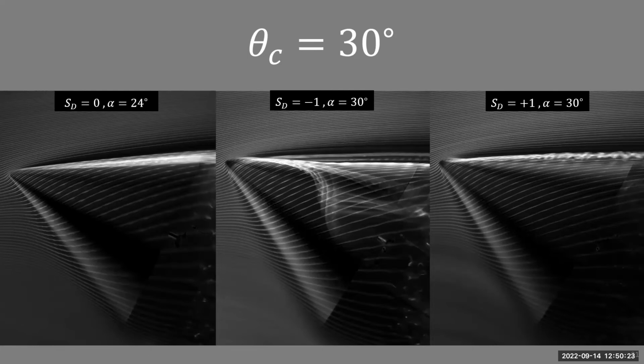So if we go back to Kobayashi, it's a better description. As you progress along the length of the cone, the transition from laminar to turbulence is governed by two parameters: the local Reynolds number and the rotation parameter. As you're progressing along the length of the cone, the diameter is increasing, hence your Reynolds number is increasing and your rotation parameter is increasing. And so at a particular location in Reynolds number, you have this transition, and beyond that, it becomes turbulent. I wasn't able to characterize fully from our streakline images where that happens, but we gave some convincing evidence that there's something interesting going on.